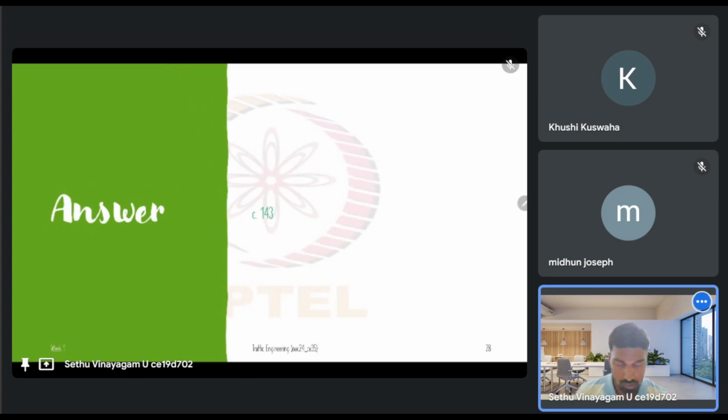What are we given? We are given the average spacing. So S average is 7 meters, and this is in the jam condition. We want to calculate the density, and because this is jam condition, we can call it Kj, which is the usual notation we use to represent jam density. How do we calculate it? The density is in terms of number of vehicles per kilometer.